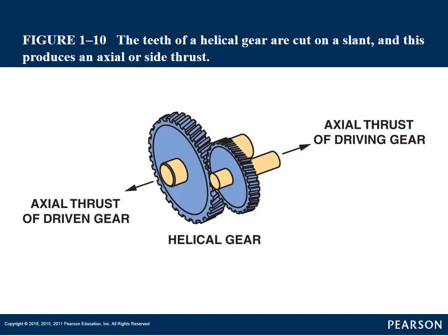they're transferring where the input power comes in and we're transferring it over to, say, the final drive or the differential of your transaxles. You might see spiral cut gears, pinion gears, and sun gears in an automatic transmission. In our planetary gear sets, they will have helical cut gears like this.